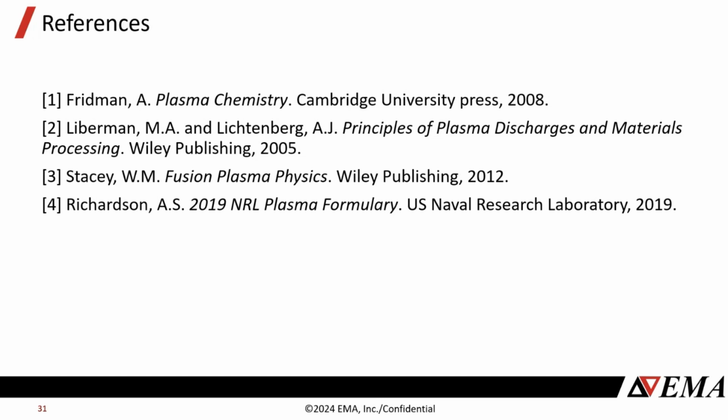Yeah, so for solid dielectrics, we actually have a different model, which uses stochastic treeing. In that case, we'll check to see if some node or some portion of your solid dielectric has an electric field that exceeds the dielectric strength of your material.